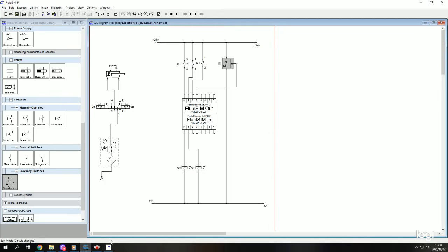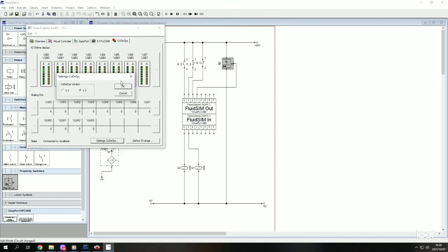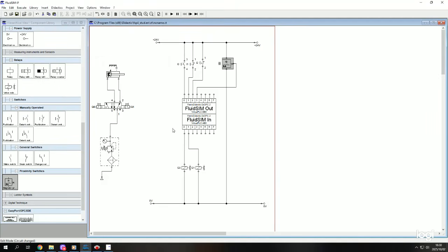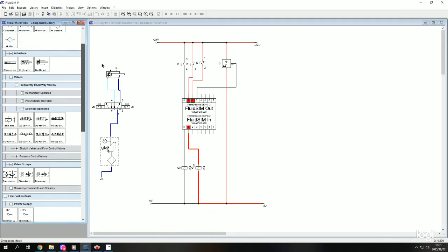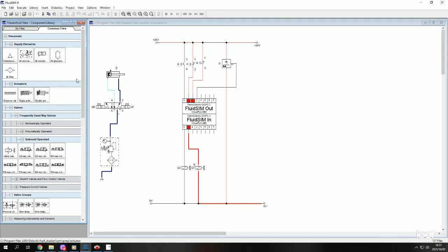So let's double check here. Localhost, yes. Let's simulate. When I press my push button, it should advance, and when I release my hand, it should retract automatically because of this magnetic sensor. Yeah, so it does exactly that. When you insert a one-way flow, you'll be able to see how fast it's moving to advance and retract. You can even play around with it and say you want it to advance slowly or to retract faster. So yeah, it advances and retracts automatically.